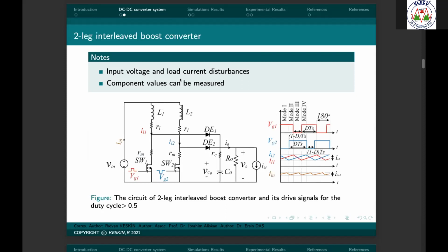Normally the internal resistance of fast recovery diodes or SiC or GaN type diodes is low, but the most important parameter for the power loss calculation is the forward voltage of the diodes, which sometimes reaches 1.6 or up to 2 volts, and this can really challenge your equations.